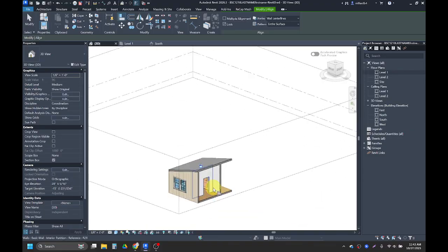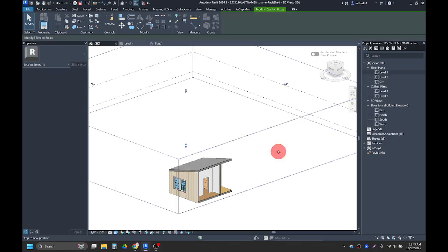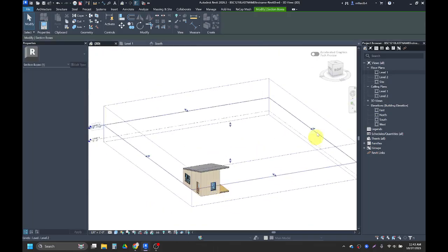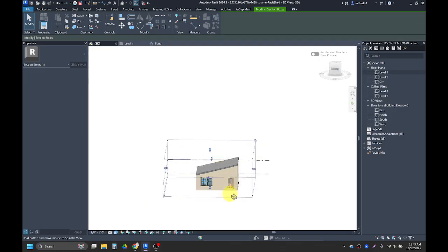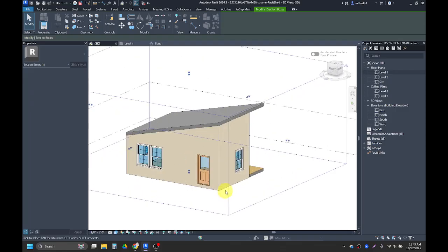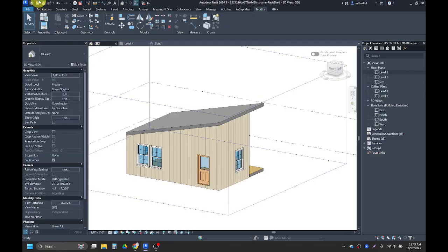And so now I have a ceiling, or a cathedral style ceiling, in both of those rooms. I'll hit escape a bunch of times just to get out of the ceiling tool. I'm going to leave my section box active just because I use section box quite a bit when I'm working. And then I'll make sure to save my work. And then I'll see you in the next video, in which we are going to put in a foundation and a site.